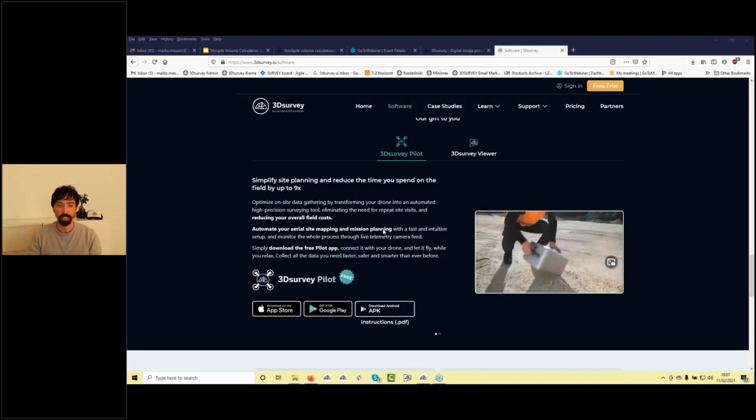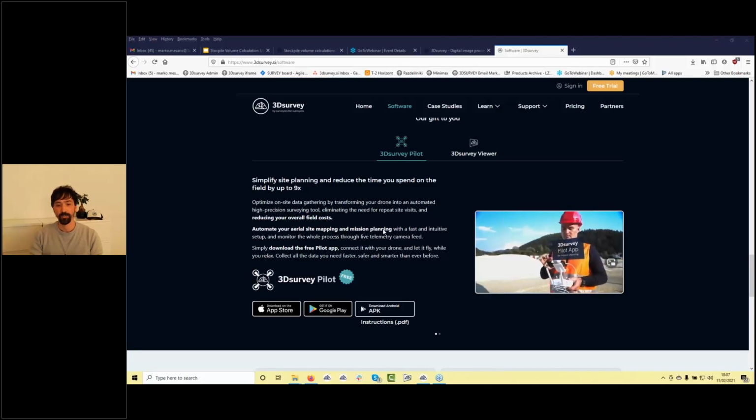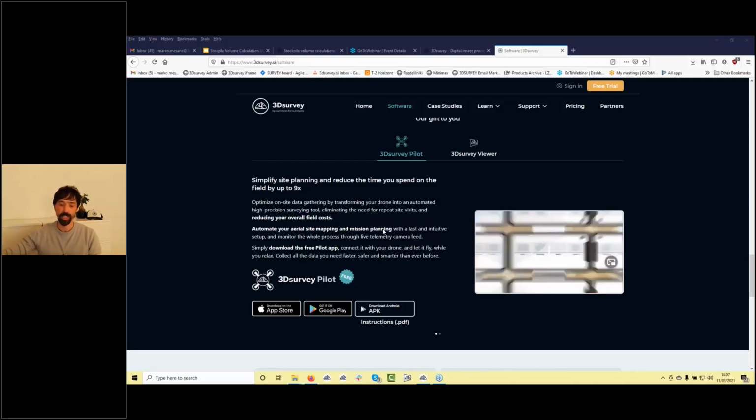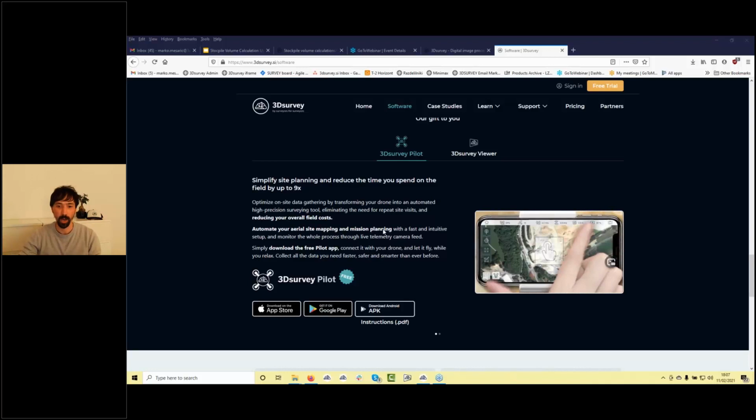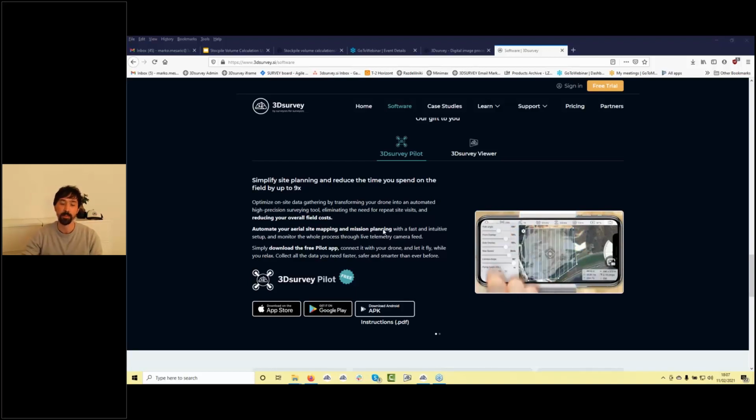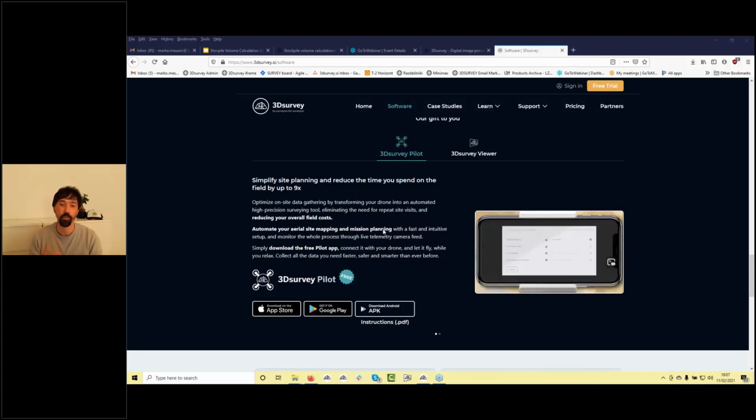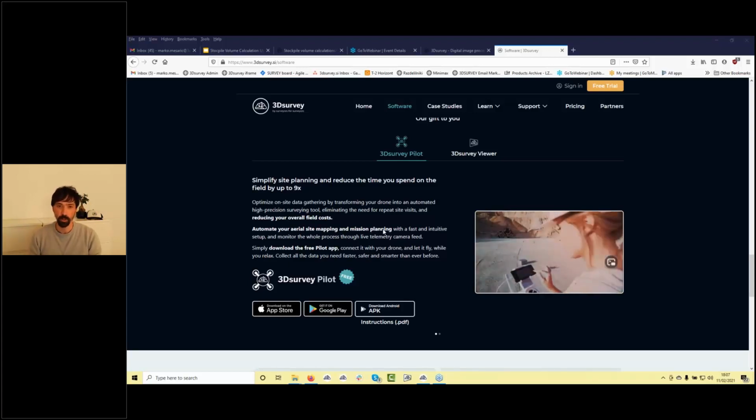Of course, it also works with the Phantom 4 Pro, and just for comparison, if you have an area like 1 by 1 kilometers, with the Phantom 4 Pro you would probably need 20 ground control points. With the Phantom 4 RTK you need, in the best case scenario, just 4 control points, in the worst case. In most cases, just a single ground control point helps you with the calculation.